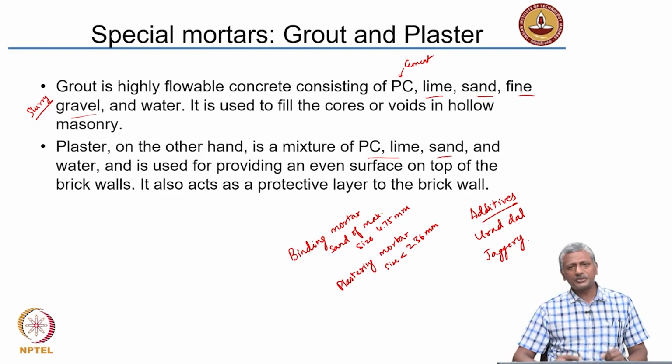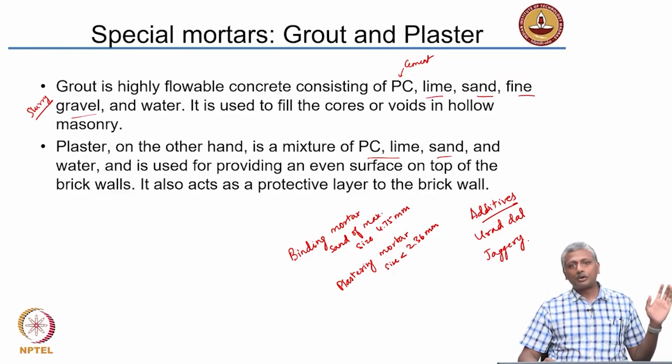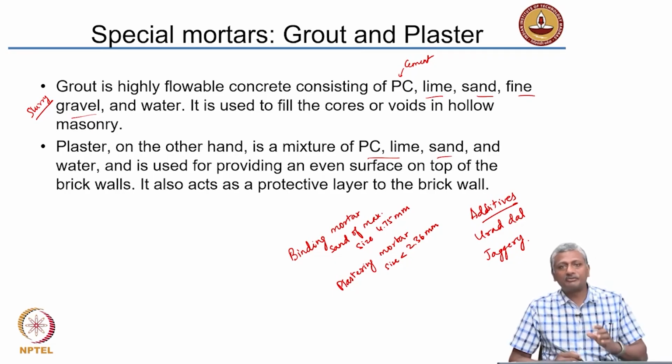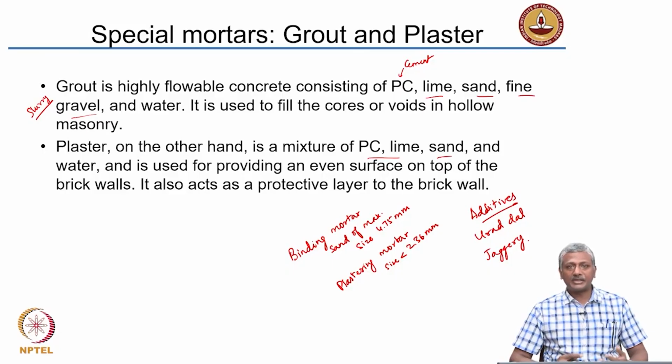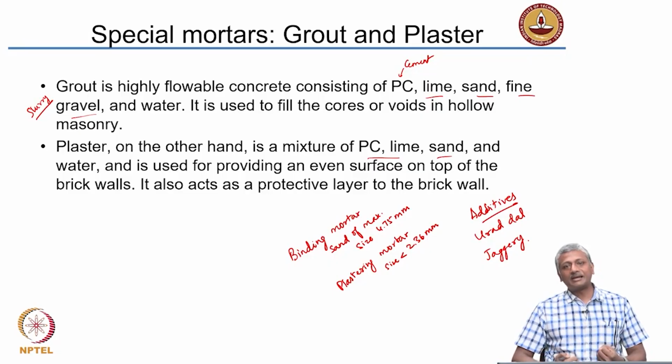So, depending upon the application and depending upon the geographical location, there are practices that have thrived, that have actually stuck on from age old times, which are still being followed, especially with the construction practices with lime. So, you will see that depending upon the geography, depending upon the location, you may actually get very different practices as far as lime mortar preparation is concerned. There are even examples of people having used blood in lime mortars. It turned out that blood was a very good water retentive material, so that ensured that the lime mortars were consistent and behaved nicely.